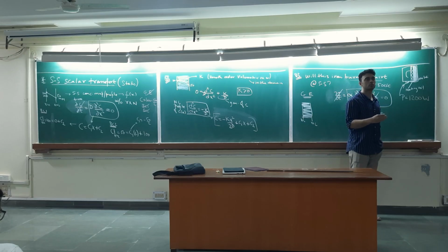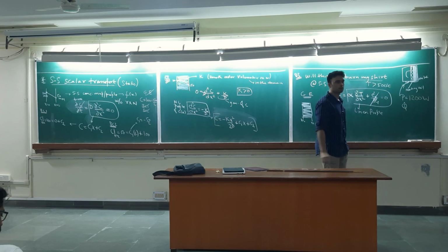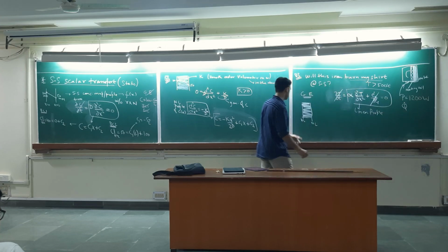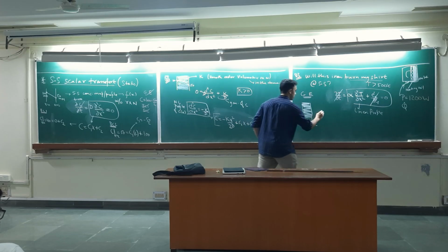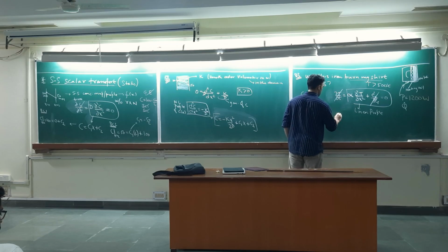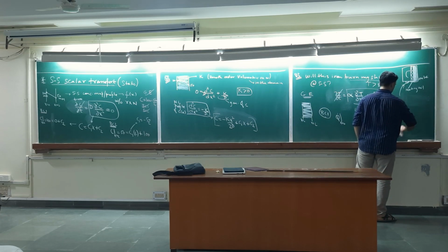What is another heat transfer quantity which has units of watts? Q or Q dot, right? So is Q dot provided at x equals 0? Okay, so let's write down boundary condition 1. Q dot at x equals 0 is, let's call it power for now, because I don't want you to do any calculation as of now. Let's call it P, and let's say it's known.